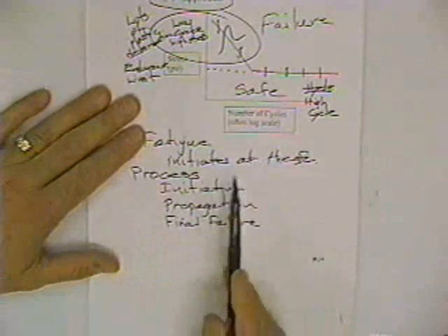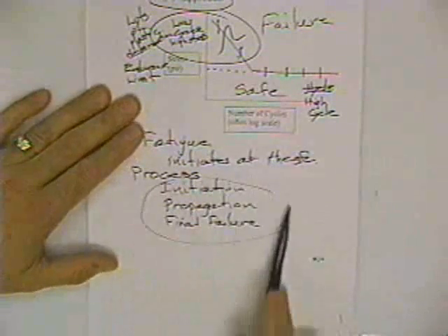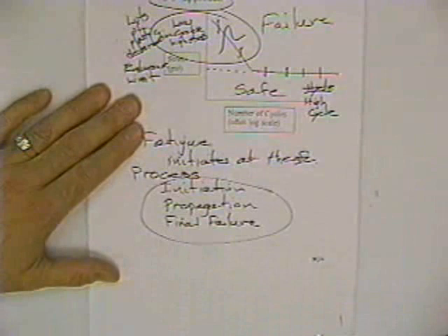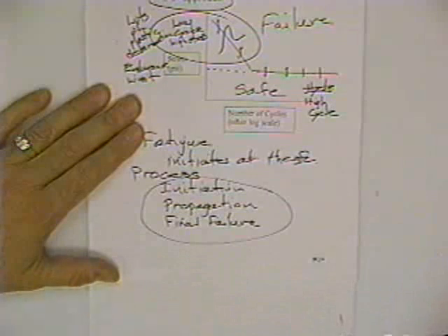And there are some techniques where you can use fracture mechanics to monitor cracks that are in materials and don't have to take something out of service because there's a crack in there. There are steam generators, airplanes, railroads that move, fly, and generate electricity with cracks in, but they are safe to use.